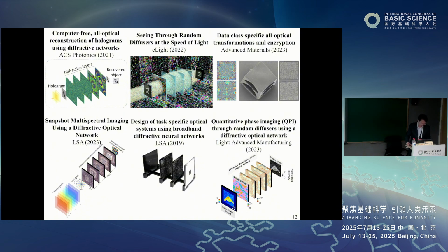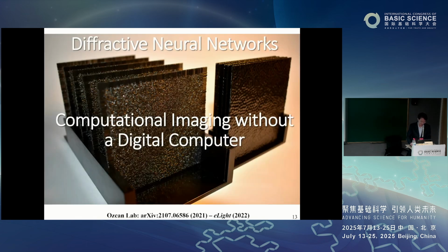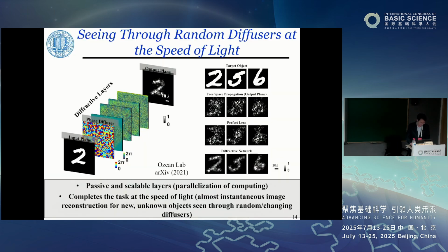By integrating large numbers of modulation elements for large-scale optical computing, our architecture, as far as we know, is the first optical computing system capable of achieving optical classification with high accuracy on the MNIST handwritten digit database, which includes 60,000 training images and 10,000 testing images, with 10 labels from 0 to 9.